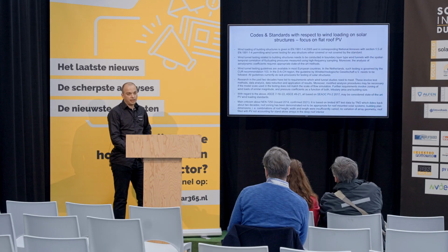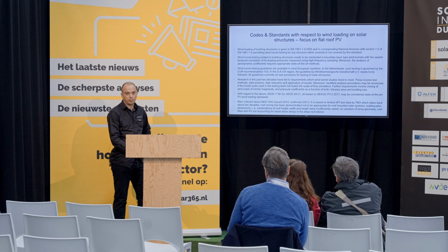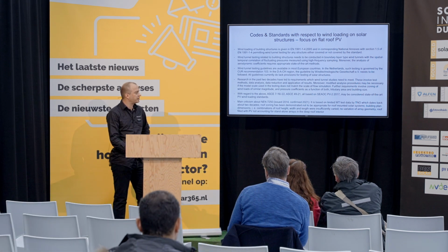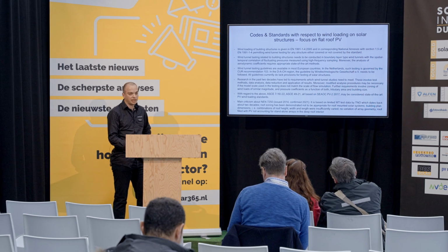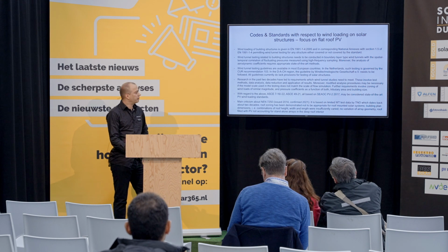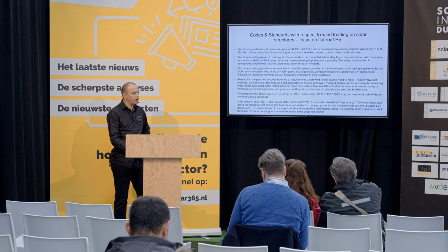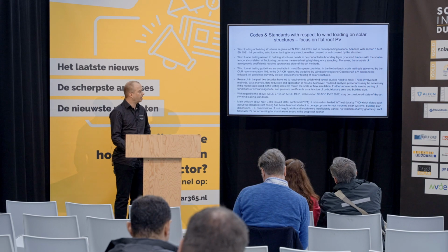Wind loading of buildings and structures is given in the wind loading part of the Eurocode, EN 1991-1-4, and in the corresponding national annexes. In each national annex, there's a section 1.5 defining the requirements for wind tunnel testing. A common misunderstanding is that only structures can be tested which are not subject of the standard, but that's not true. Basically, any kind of structure can be tested.